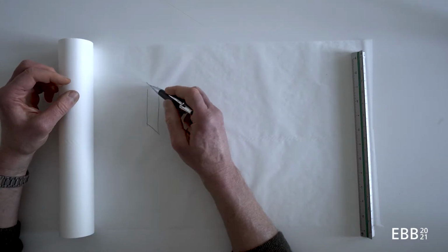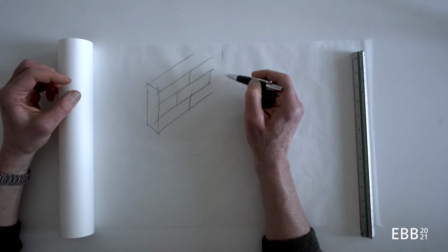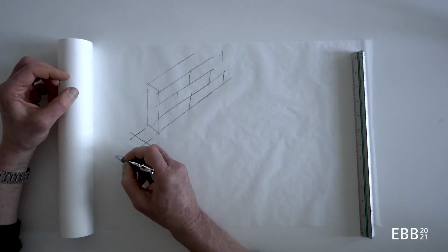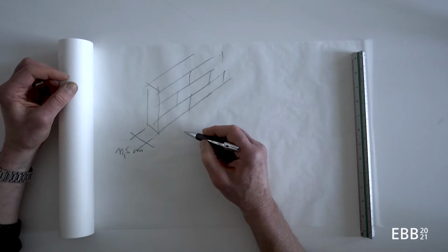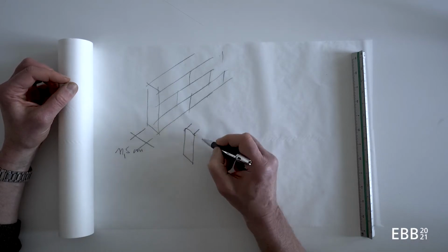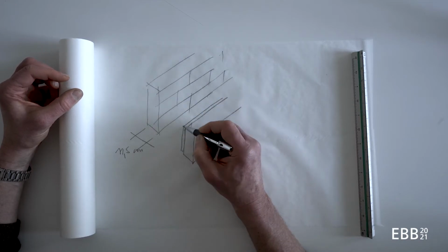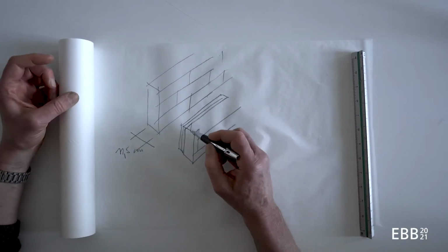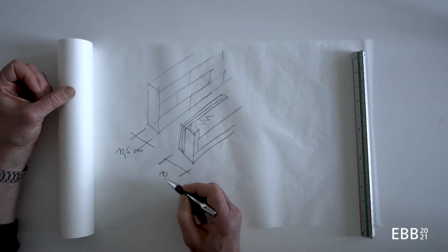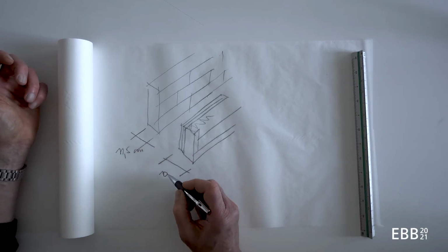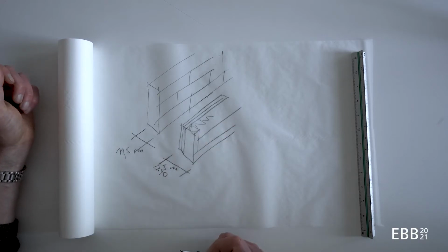One would be a masonry wall. So this would be normally, in Germany at least, around 11.5 centimeters wide. Then we had the second solution, which was metal or wood profiles, and these would be connected with gypsum board, with insulation in between. And this then would be around 10 centimeters with double plating and 7.5 centimeters with simple plating.